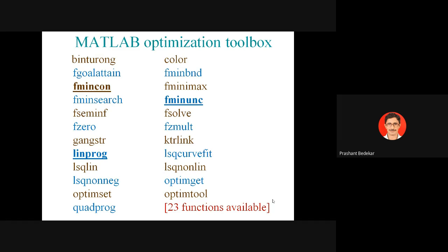linprog, which is used to solve linear programming problems; fminunc, which is used to solve non-linear unconstrained optimization problems; and fmincon, which is used to solve non-linear constrained optimization problems. So let's begin with a linear problem. linprog, that is the command. linprog stands for linear programming.